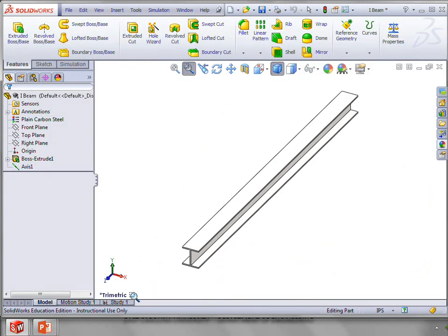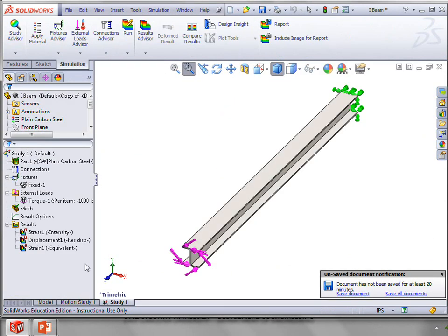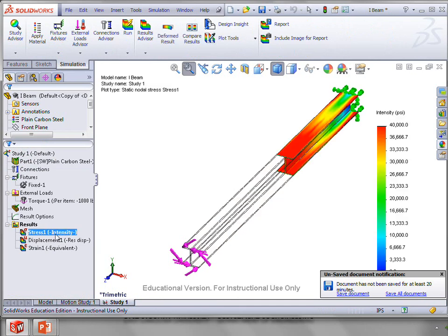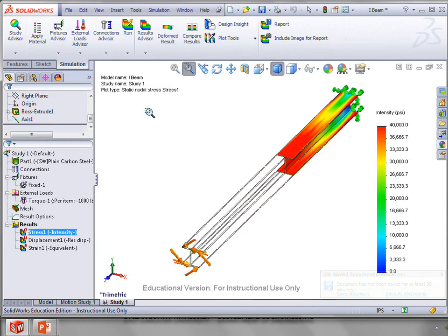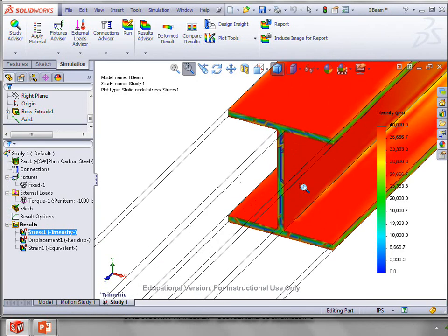But even something like an I-beam, which again is selected to resist bending, if it's going to be subjected to some torsional loading because of how the loads apply, you do have to be very careful, because you will end up with some very high stresses due to applied torsion.